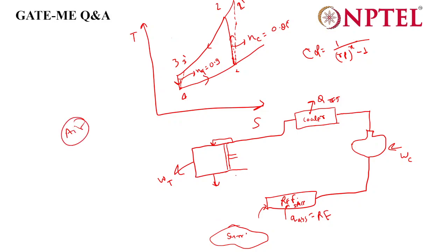Let's suppose now the working fluid is argon. Then you cannot reject that argon to the atmosphere because argon is somewhat costly. Air is available in more than sufficient amount, so we can suck it again and reject it. Because of the effect of gamma, what is gamma? Adiabatic index, or adiabatic exponent, you can say.